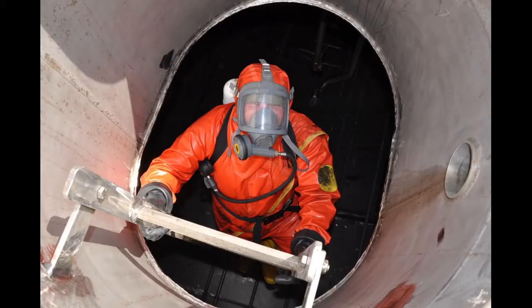Unfortunately, every year, sewage workers die from confined space injuries. What happens is that in a confined space, the atmosphere can become compromised, either toxic or anoxic. In these conditions, if a worker is not properly prepared, they can quickly succumb. These accidents often lead to multiple fatalities.